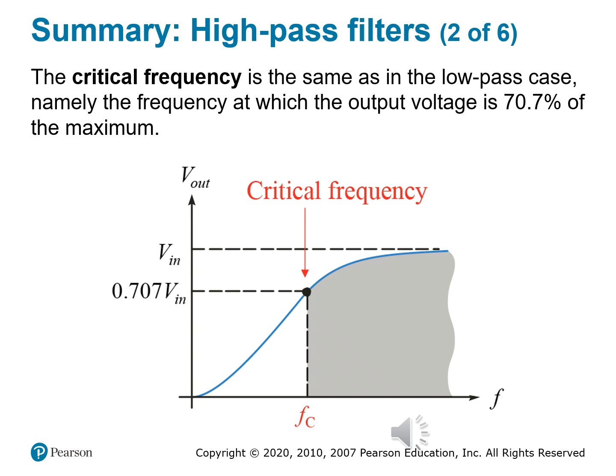So the negative 3 dB point and 70.7% of the input voltage, they're describing the same point. Again, it's the gold standard in electronics. But what happens at that critical frequency? Let's look at the graph. Below the critical frequency, your signal is being blocked, it's being attenuated. At exactly the critical frequency, you get 70.7% of your input.